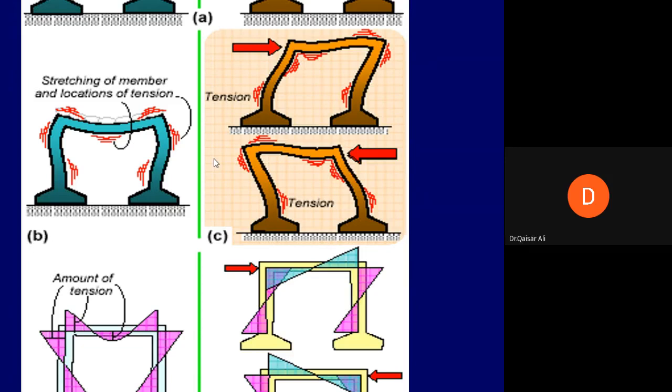By additional bending moments, I want to say that in the top side of the beam, previously there existed some bending moment, but earthquake will give you additional bending moments at those locations on the top side of the beam. But on the bottom side of the beam, you didn't have any bending moment before the earthquake forces. Now, after the earthquake forces, you will have new bending moments.